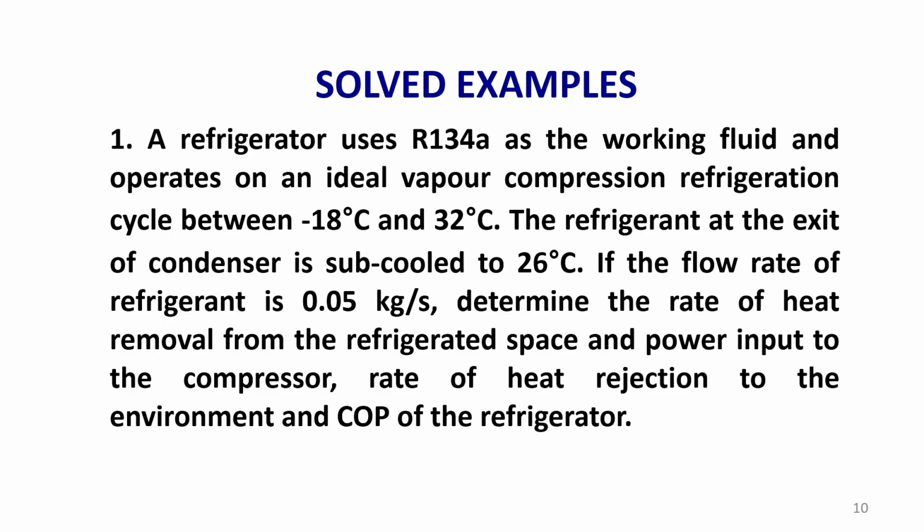A refrigerator uses R134A as the working fluid and operates. I have taken the same temperatures. If you remember the second numerical question which we solved in the previous lecture, lecture number 20, the evaporator temperature is -18 and the condenser temperature is 32. The refrigerant at the exit of the condenser is subcooled from 32 to 26. That means the degree of subcool is 32 minus 26, 6 degrees centigrade.